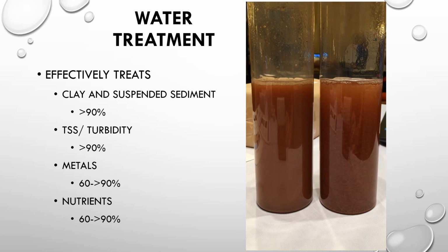So we can really greatly improve the function of sediment basins and other filtering devices like wattles, and settling devices like rock checks, wattles, dewatering bags, things like that. It really speeds up and enhances the efficiency of those other BMPs. Now, there's other things that we target: metals, nutrients. We'll talk about those more in depth in the third presentation in this series, but today we're really going to focus on clays, TSS, suspended sediment.